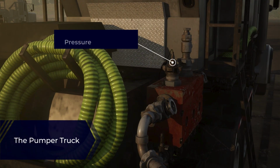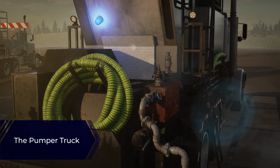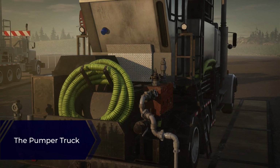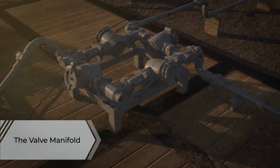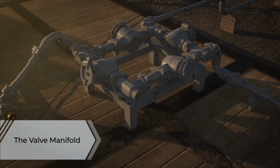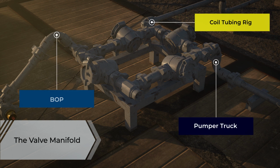The pumper truck uses a pressure transducer at the pump outlet to measure the pressure in the piping. A blue light indicates when the pumps are operating. The valve manifold consists of 4 valves actuated by an operator using a valve bar. These valves direct the flow of fluid through different sections of the rig piping, including the pumper truck, the coil tubing rig, and the BOP.